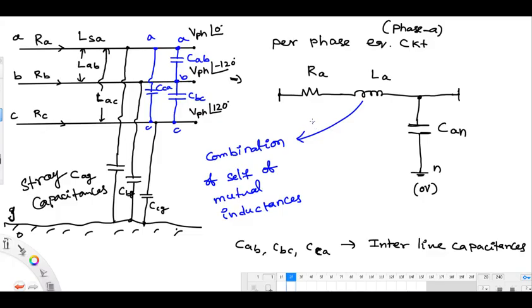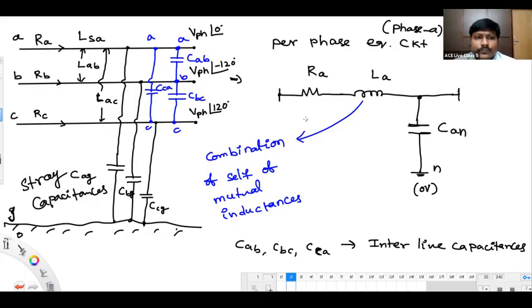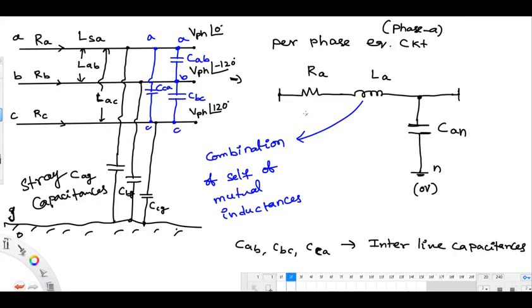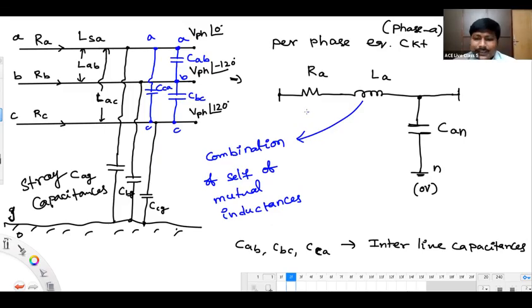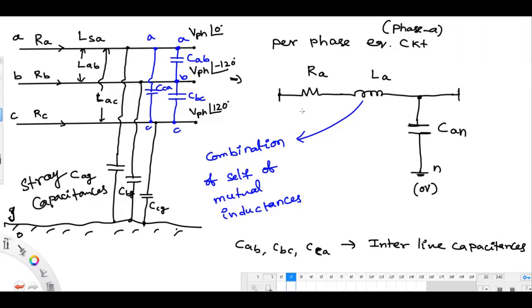In rectangle shape, at the edges E is more, so the corona effect is more. But the distance from the center to the edges is more. Not because of that reason. You have to think about electric field intensity as the rate of change of voltage with respect to distance, dV by dx.